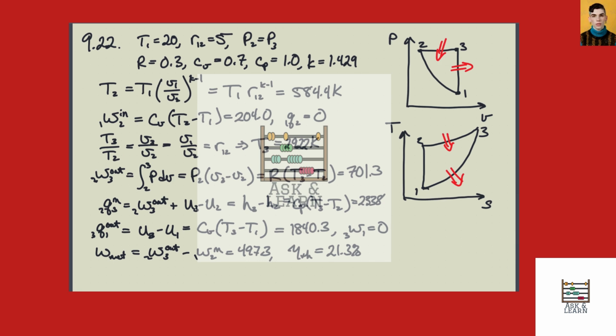And we compress the gas by a factor of 5. So the volume at 2 is 1/5 the volume at 1. And this is a line of constant entropy. So I guess I'll put some arrows in here for how the cycle goes. The numbering should make it clear, but from 1 to 2 we have this compression ratio, a factor of 5 there.